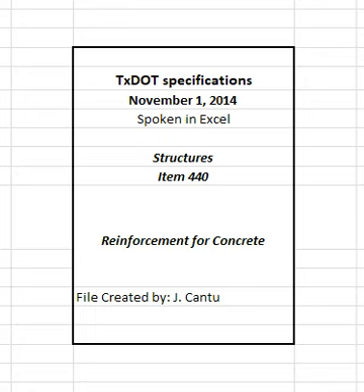Provide sample certification demonstrating the GFRP bar supplier has produced bar that meets the material specifications two months before fabrication. Furnish certification upon shipment that the GFRP bar supplied meets the material specifications. 3. Construction. 3.1 Bending. Fabricate reinforcing steel bars as prescribed in the CRSI Manual of Standard Practice to the shapes and dimensions shown on the plans.